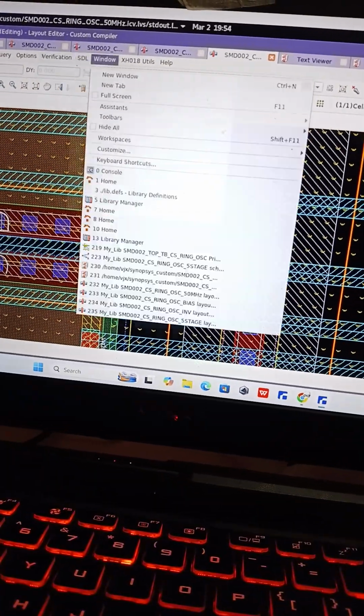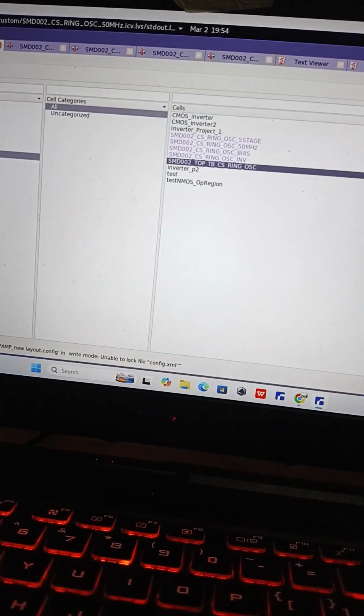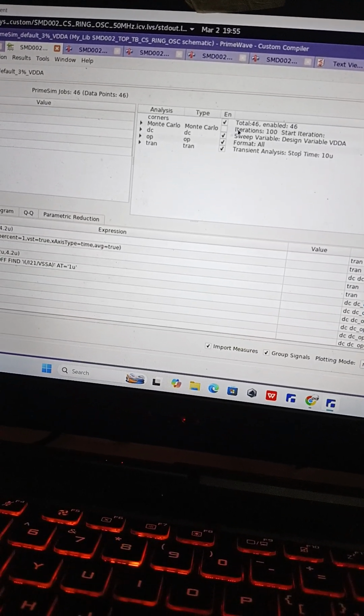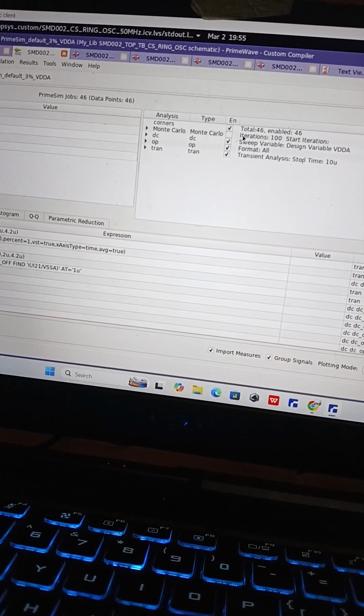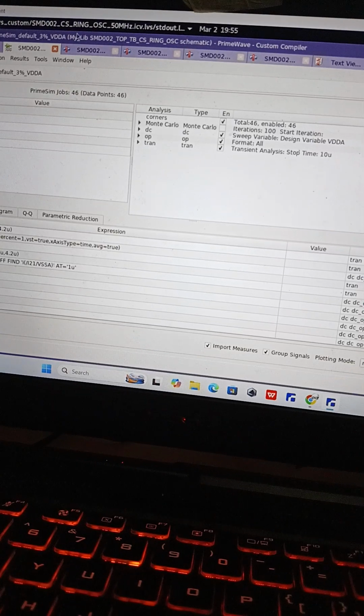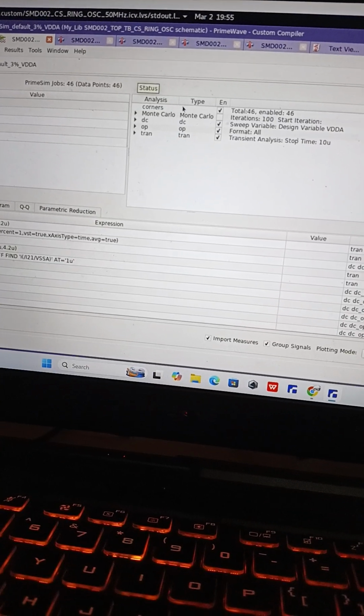After that, we will set up our test bench, check our parasitics here, and do the Monte Carlo to make sure that our chip or circuit is within the spec, within the 5 sigma that the client wants, right? It depends on the manufacturing, how many sigma they want. That's the Monte Carlo.